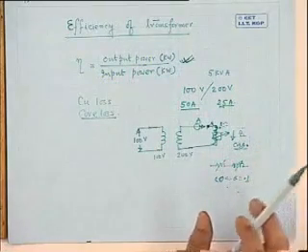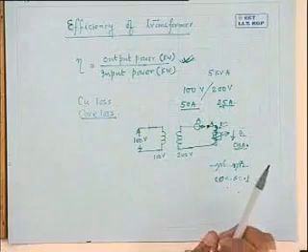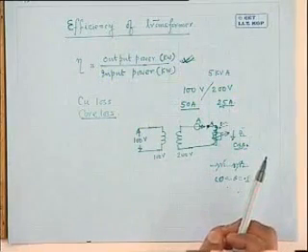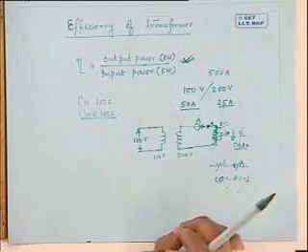You connect 8 ohm pure resistance, then also I will tell the transformer is fully loaded. Because so far as the transformer unit itself is concerned, it is carrying its rated current, because the winding cross section etc. are running to their full rating. Okay, so keep this in mind when I calculate the efficiency of the transformer.